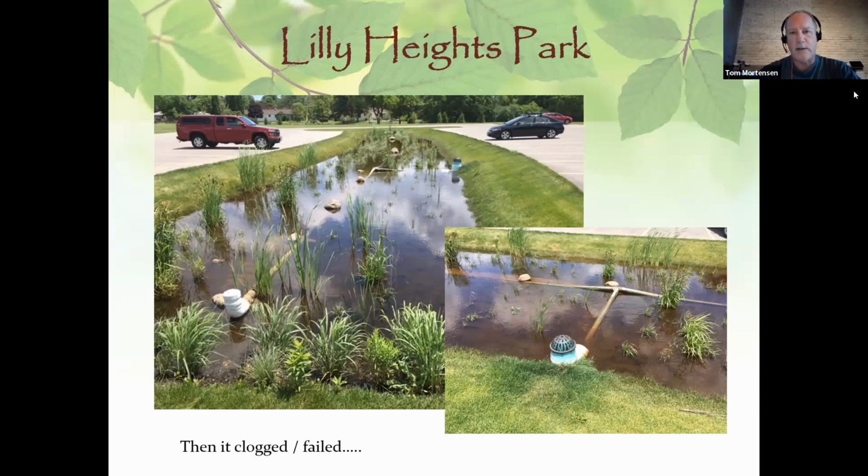this is a learning session here. What can we do? So we took out the pipe, we took out the pea gravel, we took out the fabric, we backfilled the trench with a larger aggregate that had more void spaces in it so water would move through it a lot quicker. We removed the sock off of the drain tile and the water went down immediately.